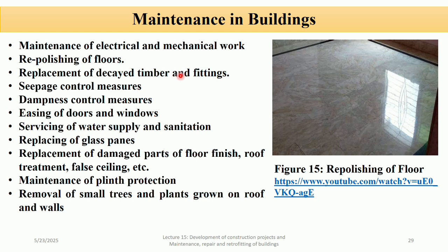Changing out rotted or termite-damaged wood components and hardware. Seepage control measures. Identifying and fixing water leakage to prevent moisture damage. Dampness control measures. Easing of doors and windows. Adjusting doors and windows to open and close smoothly without sticking.